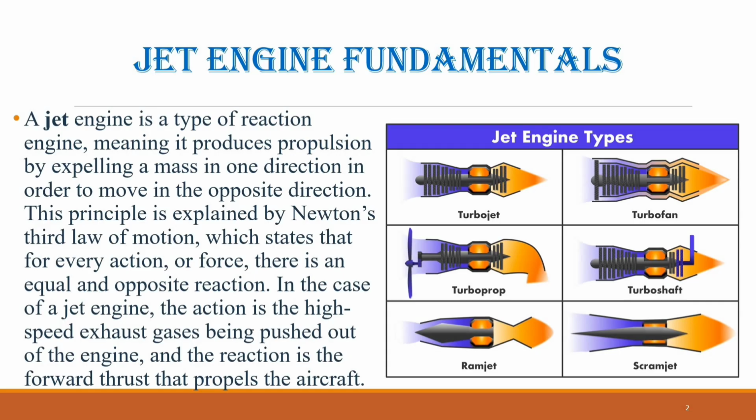This design approach leads to different types of gas turbine engines. Turboprop engines use turbine power to drive a propeller, making them well suited for slower aircraft and short-haul operations. Turbofan engines use a large fan to move a greater mass of air at a lower velocity, improving efficiency and reducing noise for subsonic transport aircraft. Turboshaft engines primarily deliver shaft power rather than direct thrust and are commonly used in helicopters. Each of these engine types is optimized to match the speed and operational requirements of the aircraft it powers.